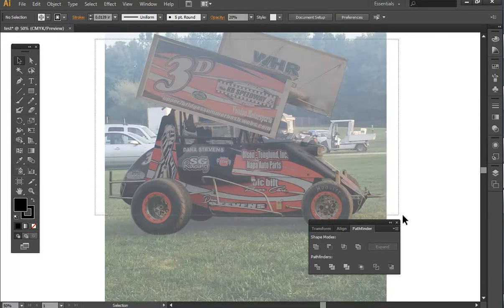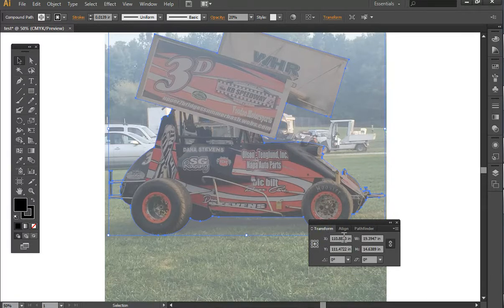And when we did this artwork, I didn't really scale it, so we need to figure out what the size is. So I'm going to draw a bounding box around it, select it, and go down here to the Transform tab, and if you look, it has the width and the height, and I think that's fine for this design. It's a pretty good size, so we could get a lot of detail in here.